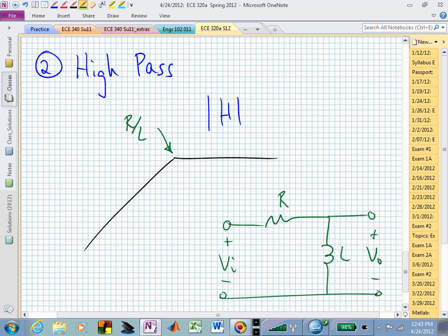So now, in terms of high frequencies, what's actually happening? Now, if you looked at the transfer function, you have SL over SL plus R. So now as S goes to infinity, the bottom and the top are going at the same rate in terms of getting large, and so they're becoming 1. So now at high frequencies, what does this inductor do? Its impedance gets really, really big, doesn't it? SL. So if this gets really, really big, you could think of that basically disappearing in a sense.